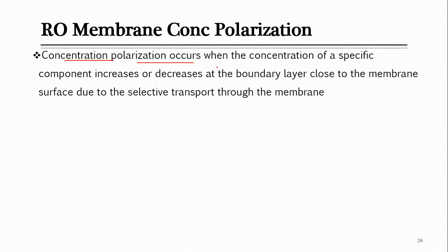So concentration polarization, as its name indicates, polarization, the creation of some pole, something like charge. Concentration polarization occurs when the concentration of a specific component increases or decreases at the boundary layer close to the membrane due to selective transport through the membrane.